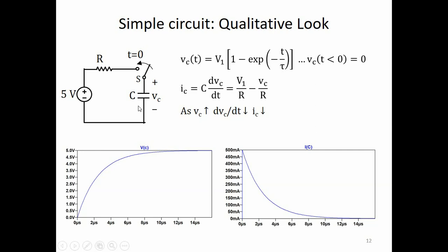The notion of fully charged does not apply if there is a current source, because the capacitor never reaches steady state. When you have a current source, the capacitor voltage is increasing linearly with time, and any function that increases linearly with time never reaches a final state. If it is exponential in time, then it is approaching some final value, and that is a fully charged state.